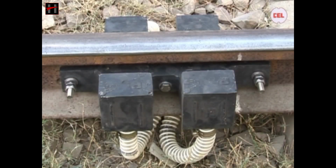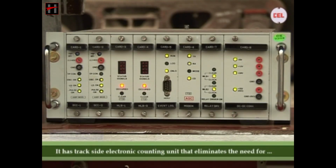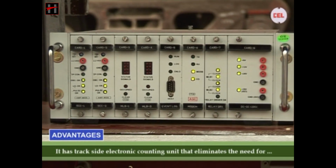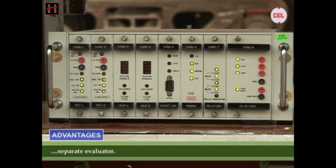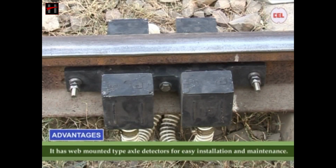The main advantages of single section digital axle counter system over analog axle counters are: the SSDAC uses high frequency axle detectors, that is 21 kHz and 23 kHz, for higher noise immunity to traction current. It has trackside electronic counting unit that eliminates the need for separate evaluator. It has web mounted type axle detectors for easy installation and maintenance.